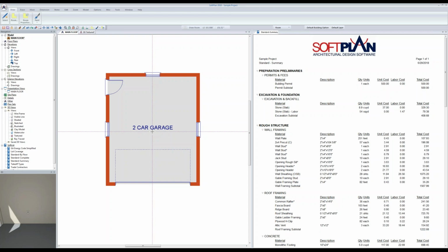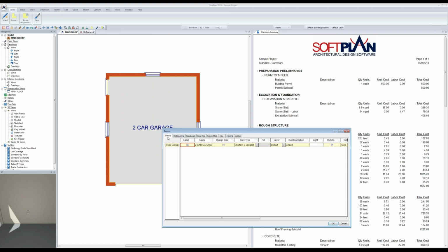It can also add, and if I edit that room, maybe give you a better understanding, a wall covering, paint, wallpaper, whatever is defined for that room. Baseboard as an option. I don't believe a garage has it. It doesn't, so we'll enable it for the garage. Let's say for this example, we can also add chair rail, crown mold, a tray ceiling, flooring, as I was discussing, and a ceiling itself. So all those elements are quickly added by defining a room.